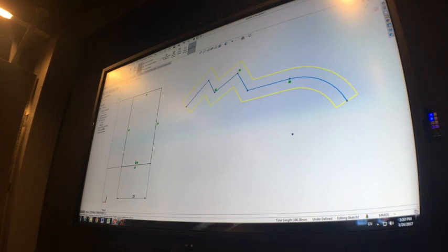And then construction geometry, this is where you can convert your existing line or your new line to construction. Construction geometry is any basic line or shape that has been converted for construction. So they're dotted lines. When they're for construction, they're not included in any features that you're using. They can be referenced as an axis or something to revolve around or extrude up to, but otherwise it's not